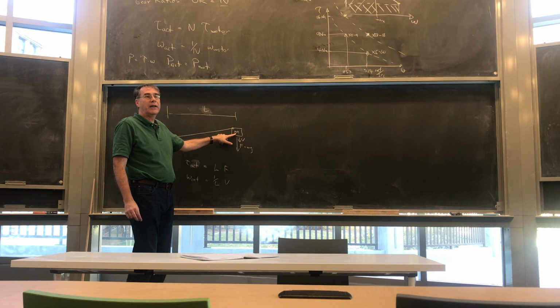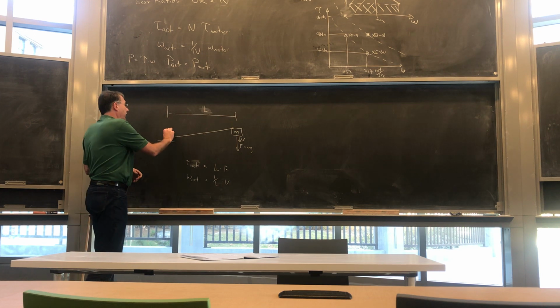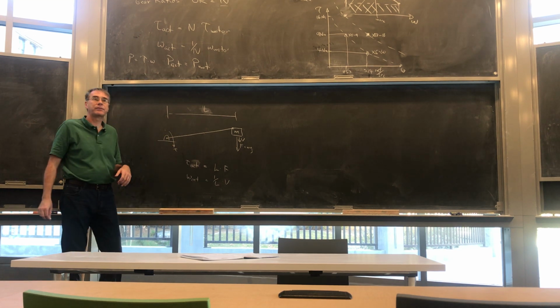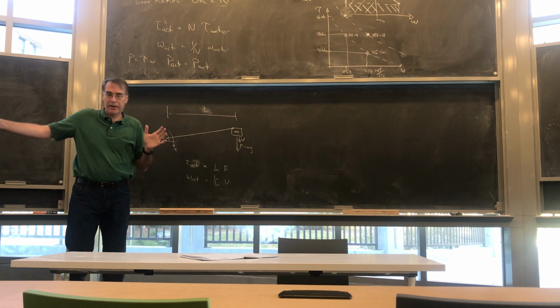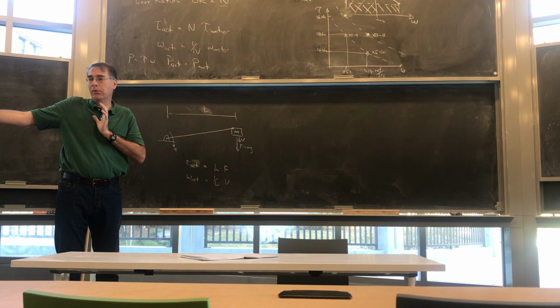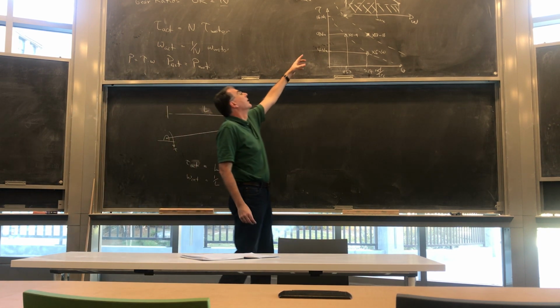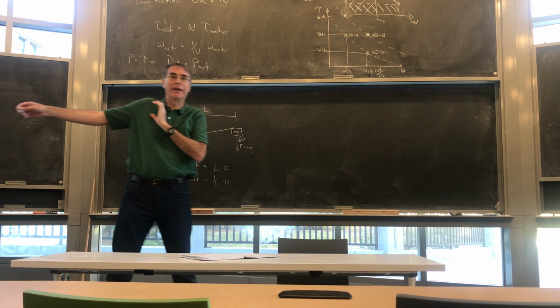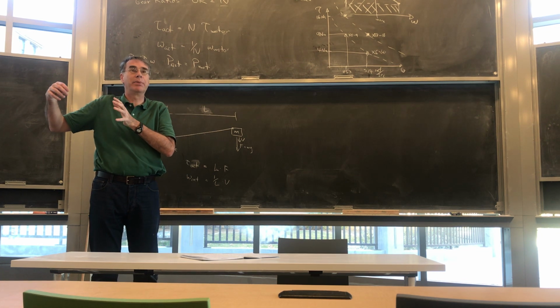The actuators weigh 300-400 grams. I put it in the homework, right? You can add up how many actuators are going to be out here, and add 50% for the links and the screws and stuff. Then give me a rough idea of how much torque is going to be on this motor. That should be consistent with how many Newton meters you have. If you think about it, 10 newtons is 1 kilogram, right? 1 meter is probably the longest that I expect an arm to be. So a kilogram at 1 meter should be 10 Newton meters. The biggest motor can do more than that, but that's basically the maximum. That's why I keep saying we're going to have a workspace and arms that are about human length. They're not going to be much bigger or stronger than that.